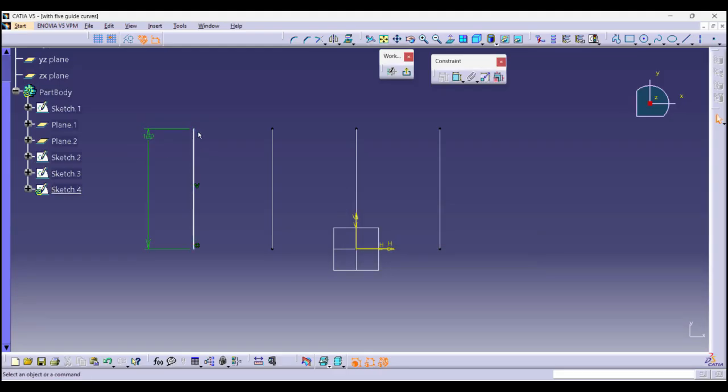It is not necessary to put this value as 120. If the length has been taken more also, it will continue adding the surface of 120 mm only, as measure of the lines having the distance as 120. But still we are going to put this value as 120 and then this horizontal distance. So we are going to take this distance as 80 mm.